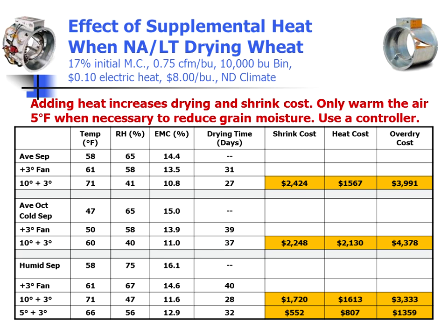But one of the things that we need to keep in mind as we're designing and operating this system is that we're always going to get a little bit of supplemental heat off of the fan. The amount of temperature rise is going to be related to the static pressure that fan is operating against. We've typically used a rule of thumb of at least 3 degrees.